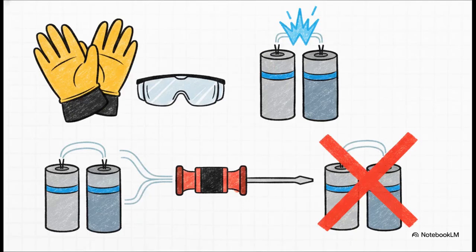So before you touch a single terminal, we need to talk safety. These are not the simple 24-volt contactors we used to deal with. You must power off the unit completely at the disconnect. But listen, you are not safe yet. Those giant DC bus capacitors we looked at can hold a lethal 310-volt charge long after the power is cut. You must put on high-voltage insulated gloves and safety glasses, and you absolutely must safely bleed down those capacitors.